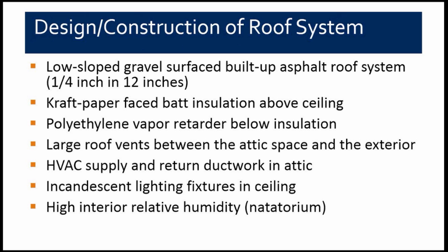It had kraft paper facing above the insulation, but it had a redundant second vapor barrier in the form of polyethylene sheeting. The double vapor barriers, and they're that close together, really don't pose a problem unless there's airflow between them, and it really wasn't the cause of the problem in this case.